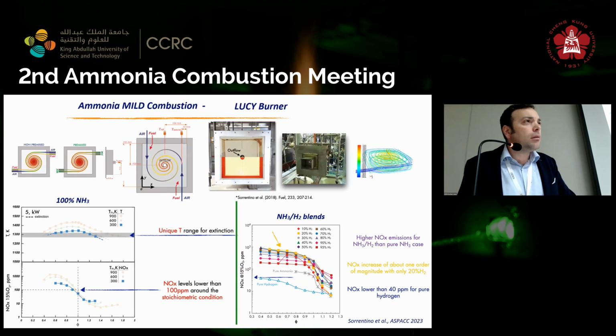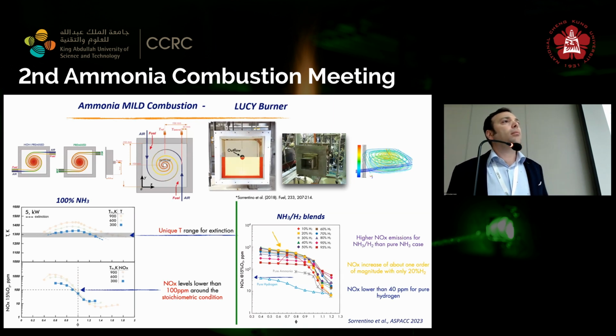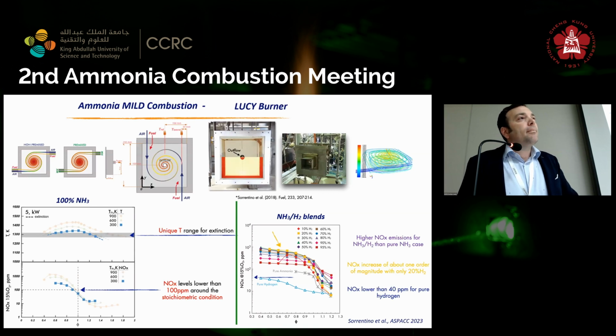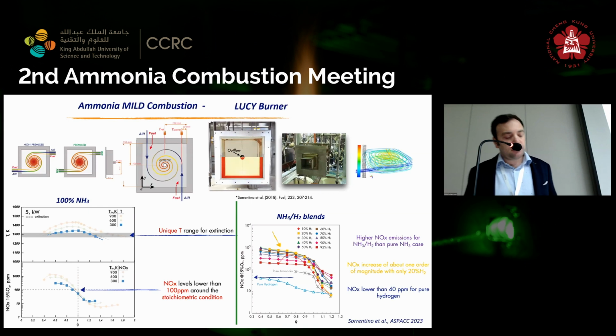This is more of a comment, just to clarify the theoretical definition and concepts. So the premix scenario is one thing, and then in the non-premix, you talked about this 1D in the mixture fraction variable. I don't think we need another new definition of that regime, because if you have a non-premix system with the air side higher than the adiabatic flame temperature, it is continuous. You have a steady solution, and this was actually identified in the classical Linan's paper. So it is a flame, and it's just a non-extinguishable flame.